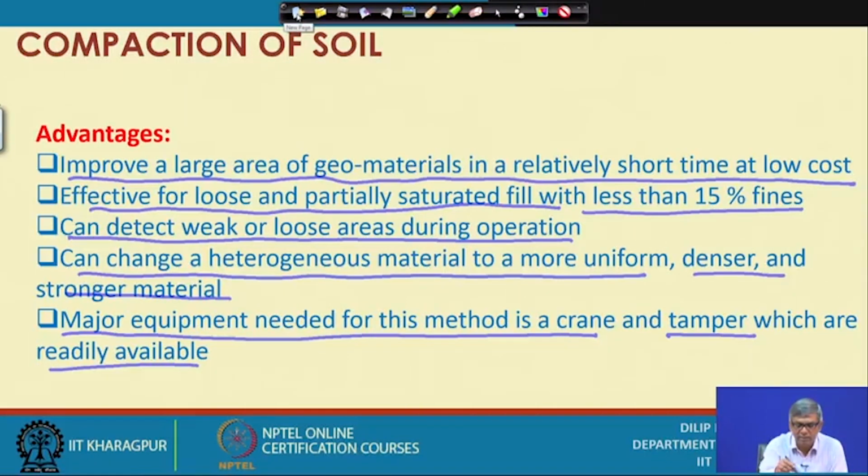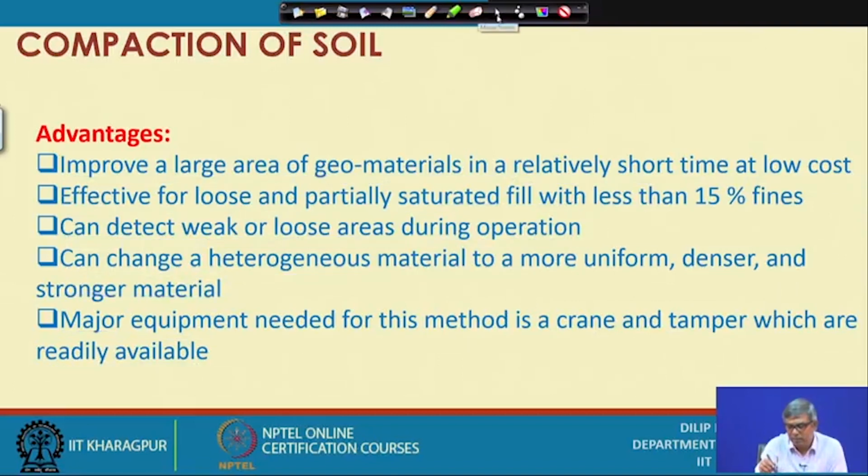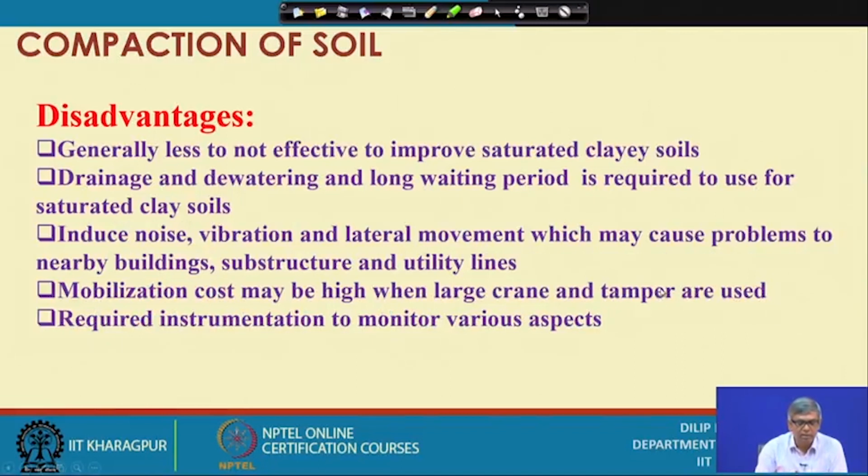So these are the advantages. And now there are some disadvantages, obviously. The disadvantage is that it is generally less effective in improving saturated clay soil. So when it is saturated soil, it is generally less effective. So that is our most significant disadvantage for this method.